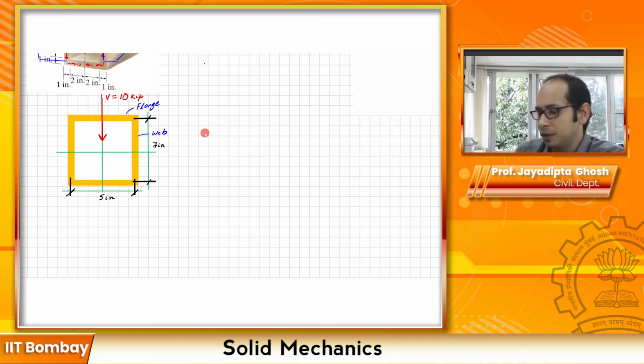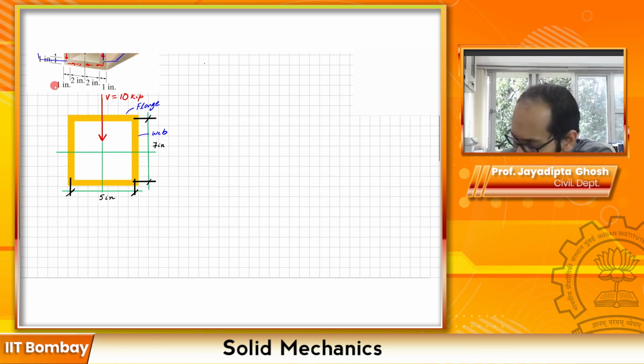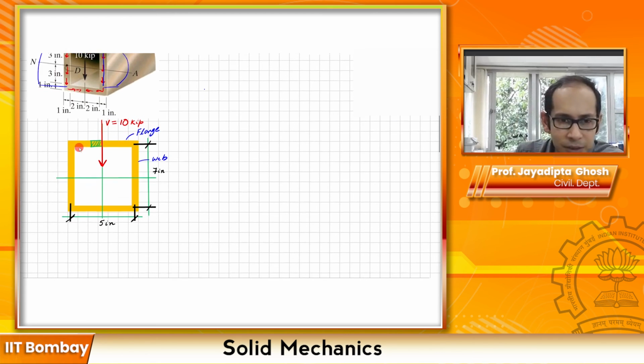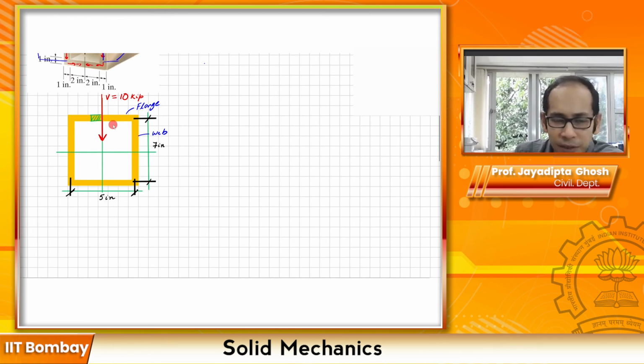So in the flange, this is the shear force which is acting throughout. If I take a small chunk, maybe up to here, right? Again, since it's a doubly symmetric section, just doing 1/4 maybe is sufficient. You know how the variation for the rest is going to be.